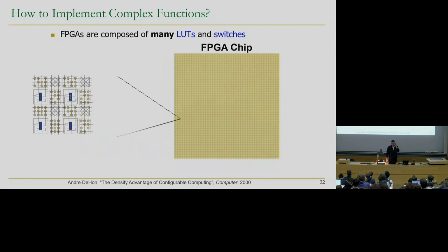Okay, so an actual FPGA chip would look something like this. It's very dense. It's packed with thousands of lookup tables, and they are configurable. Their interconnects are configurable in some way. So designing a very big circuit that will make use of those thousands of LUTs, and will need a very strict configuration of the switches, is not an easy task. So doing it manually is not feasible,